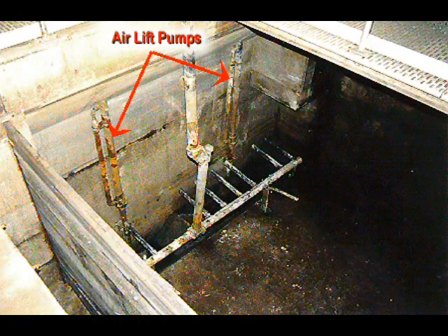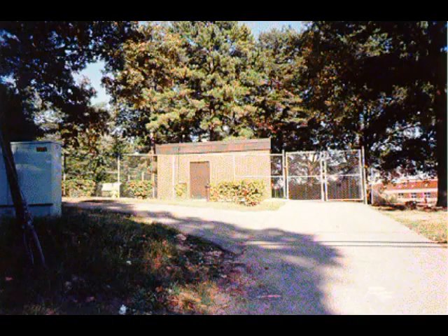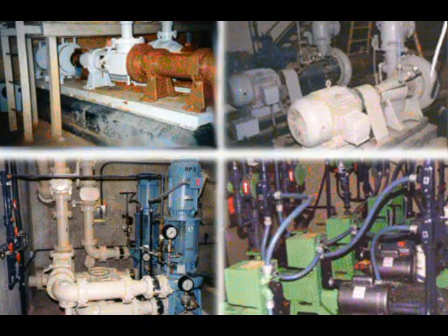An example of another type of pump is the airlift pump. They are low-capacity, low-head pumps, typically used to pump thin sludges. Later, this course will discuss the pumping stations which house the large pumps that collect and transport wastewater to the treatment plant. Pumps are the heart of the entire treatment system. Without proper circulation, the system will be ineffective and can even stop functioning.